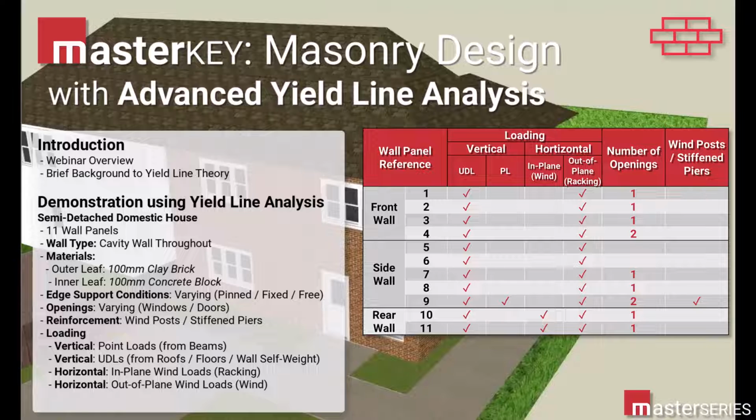But the MasterSeries Masonry module is unique versus competing masonry design software packages in that it utilises advanced yield line analysis to check wall panels laterally for out-of-plane loads, which in many cases is the critical design check for a panel. The yield line analysis method gives a much more accurate and generally less conservative design for laterally loaded masonry panels than the more traditional standard panel methods taken from both Eurocodes and the British Standards. So today I will almost exclusively be referring to the yield line analysis capabilities of the full version of the Masonry Design Module over the more traditional method, which is also an option in the software.